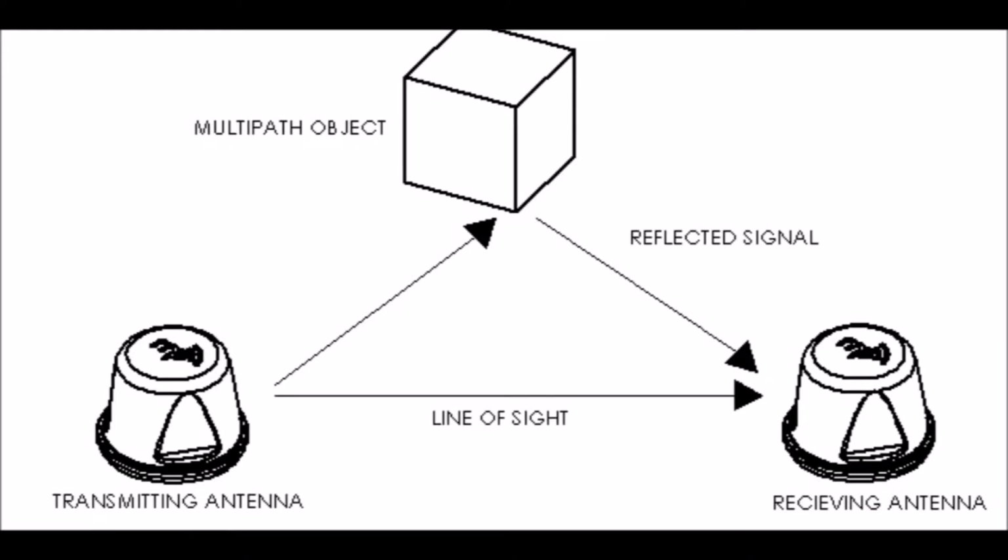Causes of multipath include atmospheric ducting, ionospheric reflection and reflection from water bodies and terrestrial objects such as mountains and buildings. Multipath propagation causes multipath interference, including constructive and destructive interference, and phase shifting of the signal. Destructive interference causes fading.